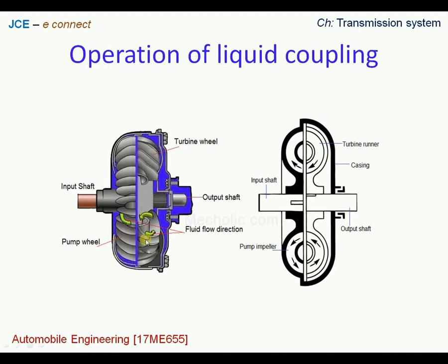On the other side we have the driven member which is connected to the output shaft, to the clutch plate, and it has splines here. We see how the fluid is pressing through within the housing. The same part is shown in side view, where the dark region shows the driving member, and the counterpart shows the driven member. So we have the impeller here, and on the other side we have a runner, in other words.